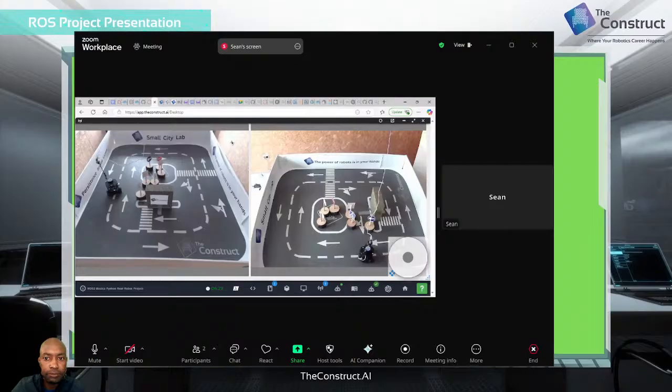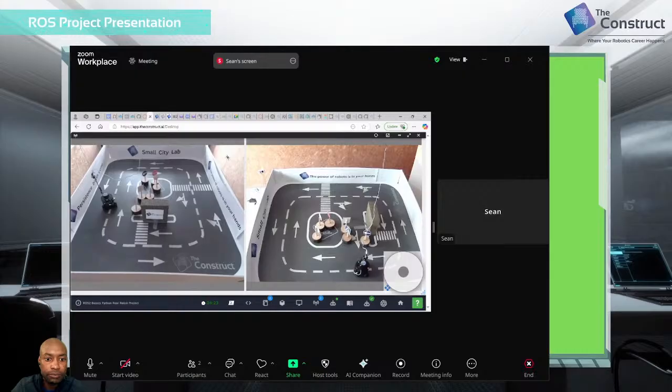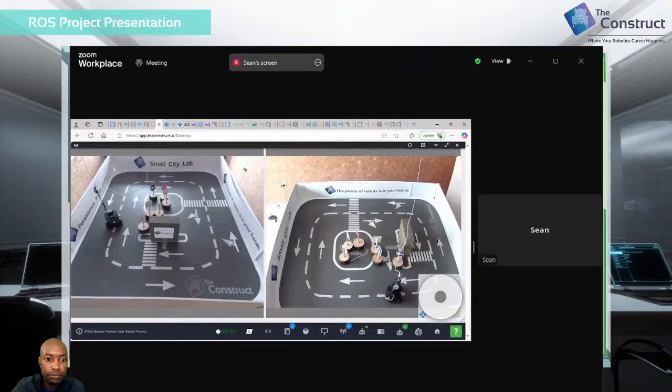What this is going to do is invoke a service, and it's going to find the closest laser scan from the 720 lasers going around the robot, and then it will move towards that, and then it will turn again to do right-hand wall following. Then it'll do right-hand wall following, giving feedback through an action.